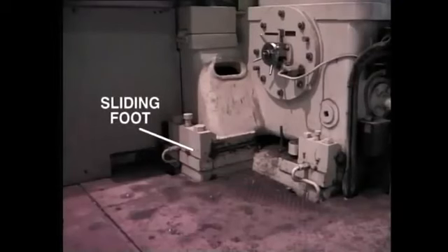In this case, the rotor contracts much more rapidly than the shell, and as a consequence will reduce the differential expansion and generally move into the negative zone. Normally, the manufacturer sets limits of differential expansion for both the negative and positive sides. The expansion position of the governor pedestal is also indicated.